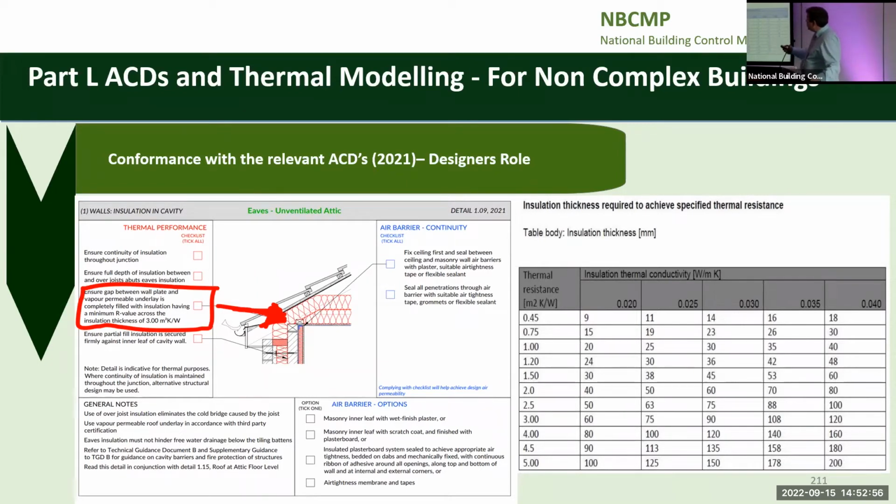And also remember that you have all the checklists on it. So the documents are very good general arrangement drawings if you put them on a paper and put your additional specifications for your blockwork, your masonry, your renders, your concrete, your cavity barriers, all of that can be specified on it, and you have a full set of general arrangement drawings and your ACDs all in the one.